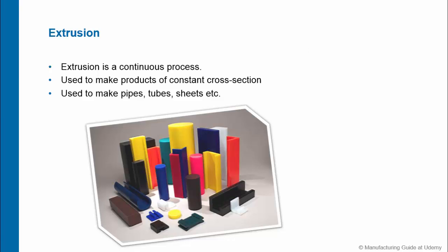If you know what extrusion is, you're in luck because extrusion molding uses extrusion with a die to manufacture products. If you don't know what extrusion is, then let me explain it. If I have a cross-section profile and if I were to add material to it to make a long product with the same cross-section profile throughout, then that process would be called extrusion.